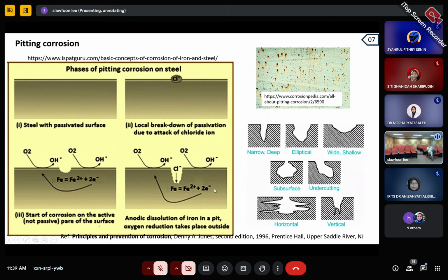So this is the difference. Don't get confused. The chloride ion doesn't decrease the pH. The chloride ion is some kind of enemy going to attack here. When you have the higher pH, you form the passive film. You form your fortress. You have the wall here to defend against the enemy entering the steel.